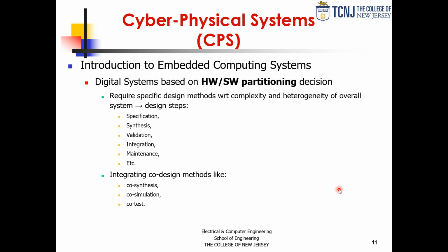But right there, in the Xilinx tool, you have your code, you have your compiler, and you have your Verilog or your VHDL, and you can link that to MATLAB as well. And through that cycle, you can start with your algorithm in MATLAB. You can export that, both the C and the Verilog, to Xilinx. You can start doing your compilation and your synthesis in Xilinx and start getting feedback as you simulate, or perhaps, if you have an evaluation board, as you download the code and the actual bit stream, you actually get some hardware feedback.